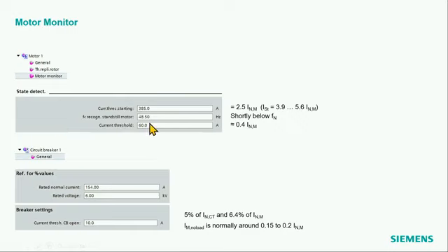Then I put here frequency. This we need to understand if we have dynamic situations like short interruption of the voltage because something is reorganized in the substation. The motor runs down and runs up again. And we detect that the motor runs down by this frequency here. So if the measured frequency goes below that value, then the system knows the motor is no longer running. This has the consequence for the load jam protection that with a restarting current, the load jam protection is not activated here, which would be the case if you don't leave the running state. So therefore we have such a frequency.